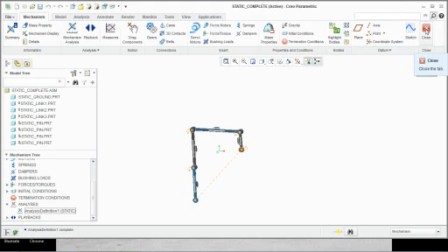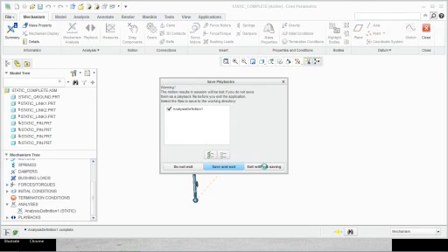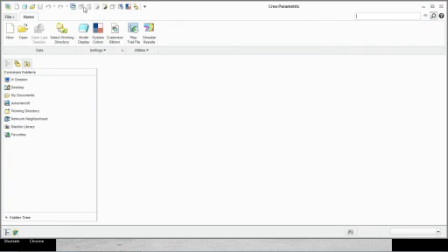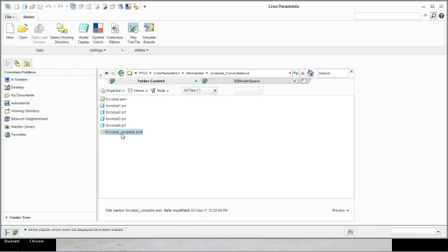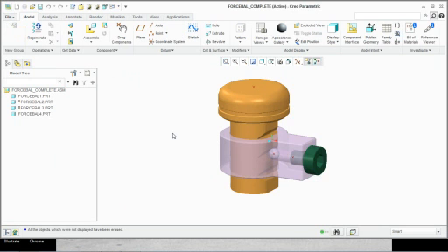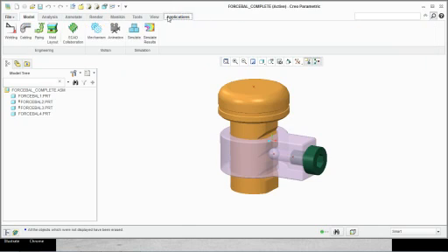Now, that's static. Let's go ahead and do force balance. A force balance analysis is an exact opposite of static analysis. It basically tells me how much force I need to apply to keep this mechanism in position. Okay, so let's go ahead, get into the mechanism.